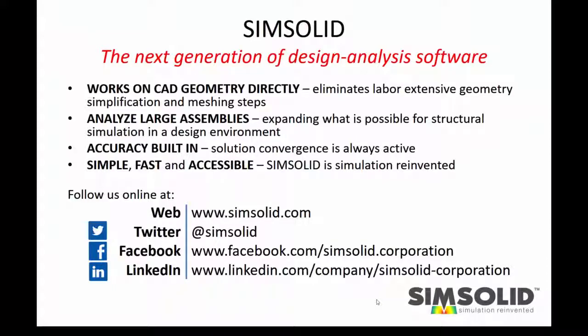Well, that gives you a quick overview of SIMSOLID. Maybe to summarize, SIMSOLID works on CAD geometry directly, without simplification, without meshing. It's capable of analyzing large assemblies. The assembly today was 85 parts, but many of our customers run hundreds and even thousands of parts with SIMSOLID. Accuracy is built in. You saw that every time we did a solution, we did multiple solution passes and measured convergence of errors. So simple, fast, accessible. That's what SIMSOLID is. We call SIMSOLID simulation reinvented.